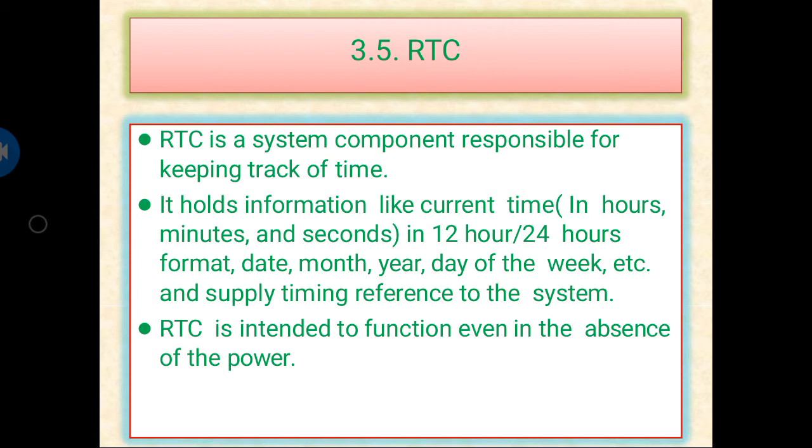kernel operations reference, and the RTC interrupts the OS kernel by generating interrupt signals on the interrupt controller. So this RTC interrupts the OS kernel by generating interrupt signals in the interrupt vector table or interrupt controller. The OS kernel identifies the interrupt request, IRQ, and performs operations like date and time updating, adding software timings, etc.